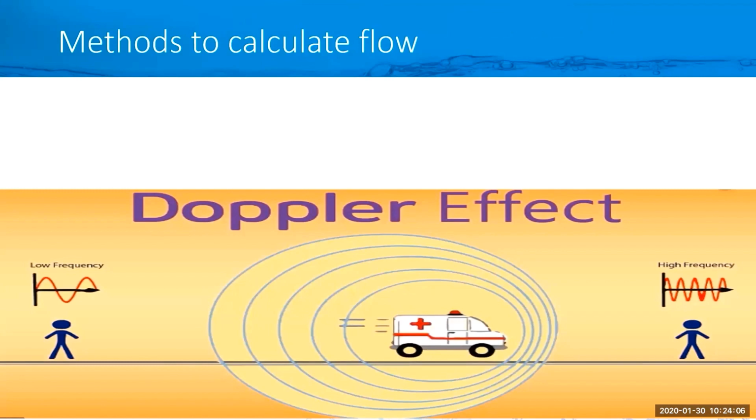With area velocity sensors like the ISCO in-pipe AV sensors, we use Doppler to read the velocity. We output a 500 kilohertz signal and read the frequency shift. The Doppler effect, as shown here with this ambulance, is that it transmits a sound, in our case a 500 kilohertz signal, and then reads the frequency shift back to the sensor.